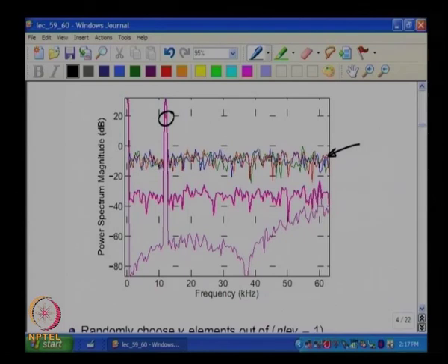This is in contrast with a thermometer decoded version where some unit elements are contributing more and others are contributing less, you understand. So, when you add all these up without any mismatch, this is what you should get, and this is the spectrum of the underlying V that you have supplied to the DAC, alright.